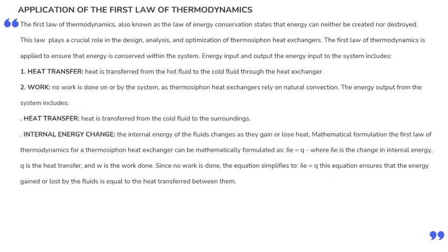The first law of thermodynamics for a thermosiphon heat exchanger has the mathematical formula on the slide. That is ΔE, the change in internal energy, is equal to Q, which is the heat transfer, plus work done. Work done is not seen in the equation because no work is done. So the equation simplifies to just ΔE equals Q.